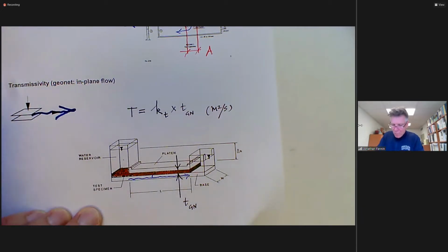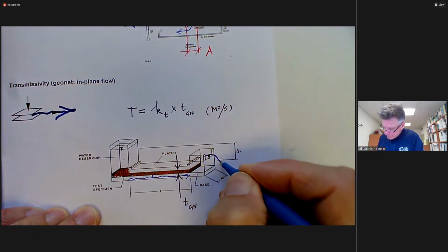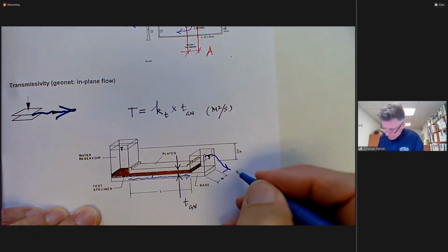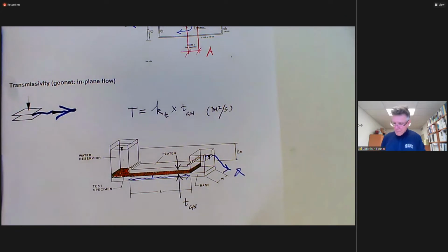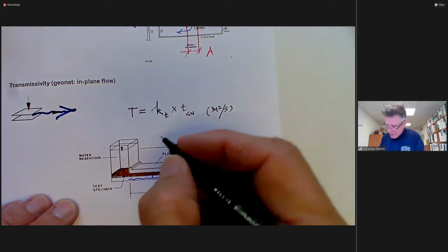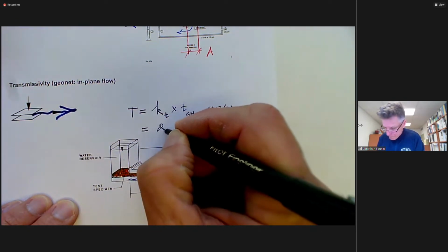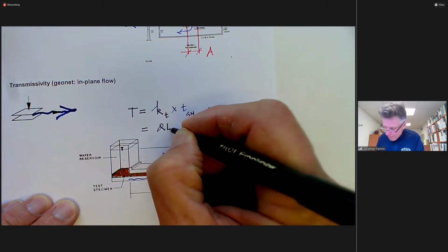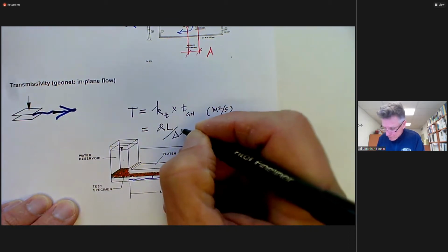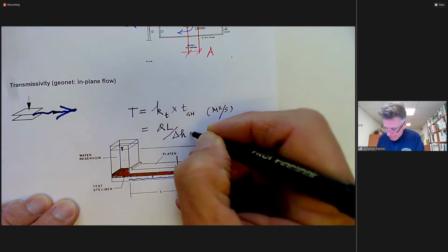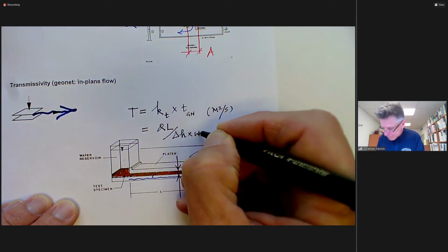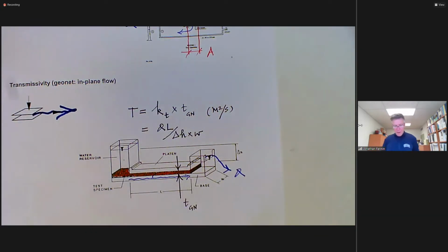And once again, we'd be measuring the outflow Q through the system. Okay. And the transmissivity would be given by Q L over delta H multiplied into W. Okay.